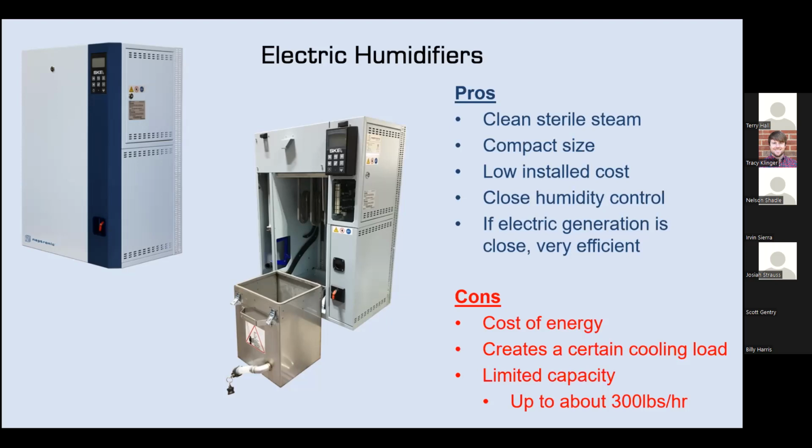The other benefit is that with that turn down, you could take a larger humidifier and basically respan the demand signal and make it a smaller humidifier without really touching any of the external controls or changing anything in your BMS. It's all very straightforward.